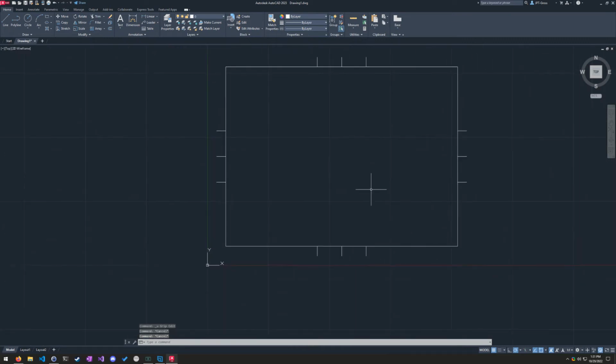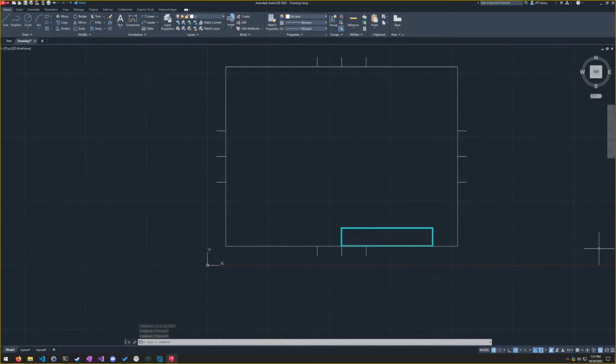Okay. I'm going to do 2 more lines now because what I want is a title block. Now, title blocks can get very, very complicated in engineering drawings, but the one that we're going to do is very simple. We're just going to have a single little rectangle here for our name. Just like we did in class, we're going to have a single little title block here for our name, the part number, and then the scale.